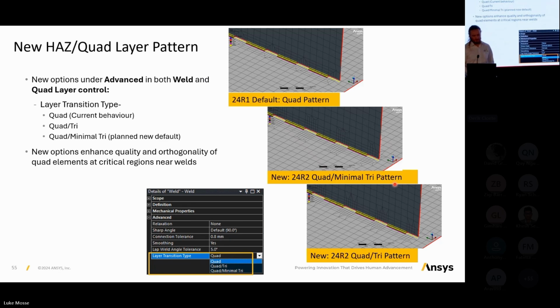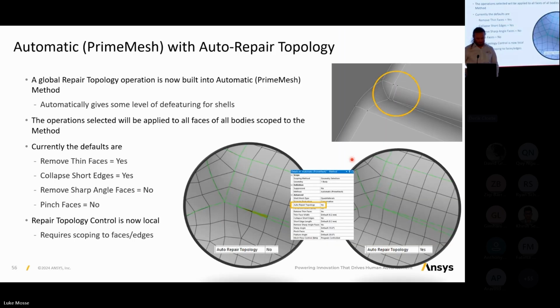And also heat affected zones. So these are back to shell elements. We often want to model heat affected zones in weld meshes. Maybe to assign a different material property because it's annealed now, or just for different post-processing. Or we just want a better quality mesh around the join region in between the welds. So previously we would get a sort of a quad dominant messy mesh around here, and now we have this lovely mapped, very regular mesh in the heat affected zone. And you can create named selections of the heat affected zone elements for separate post-processing or material assignment.